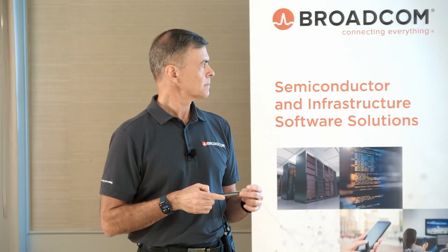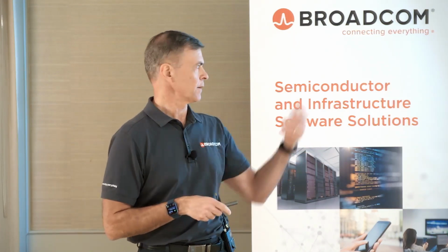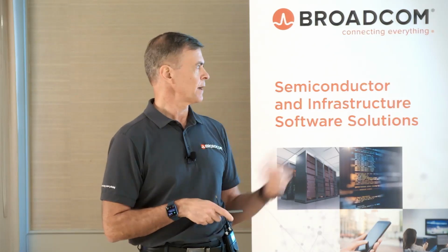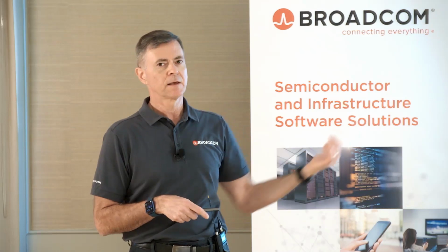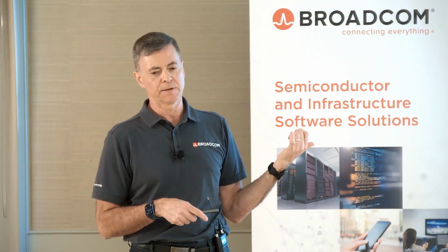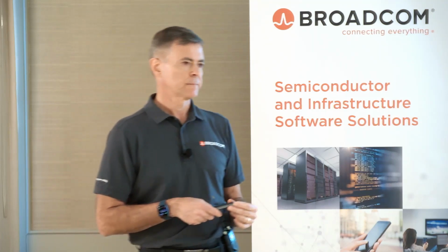Right, but my question, which I'm not phrasing well, is for actual packets coming in that I would need to process, potentially through this ASIC. Would those go straight from the NIC to the ASIC, or do they have to be brokered by the CPU in this scenario? Oh no, it could just go straight from the network through that NIC chiplet, so it doesn't have to go through the CPU. That NIC interface could also be directly to the CPU, and then you transfer through PCIe. Alternatively, it's a native Ethernet interface that you have on that GPU. Got it, that makes sense. So it's like a port on the back of it, not a separate piece of hardware.